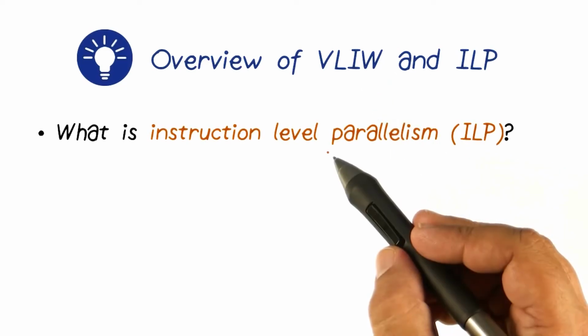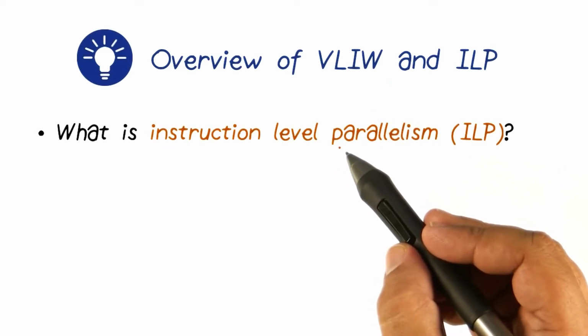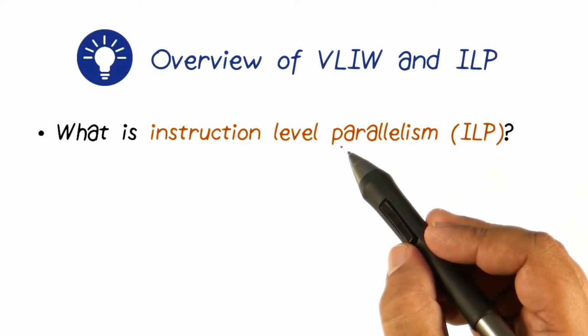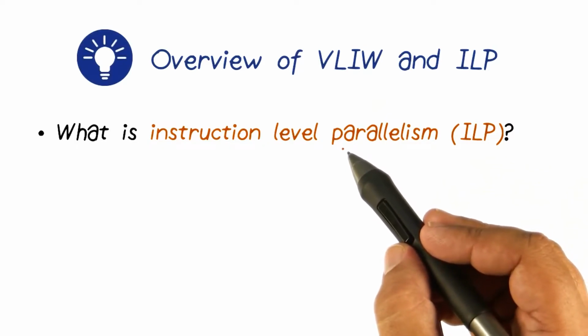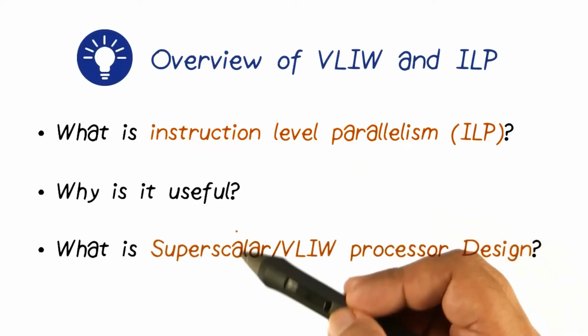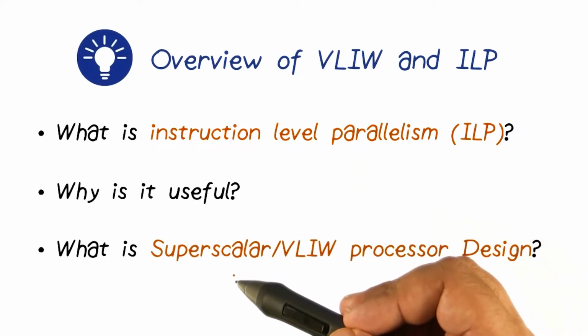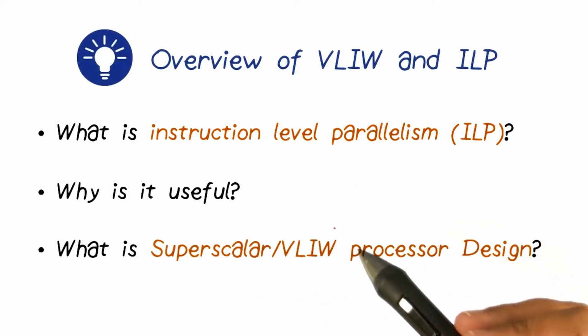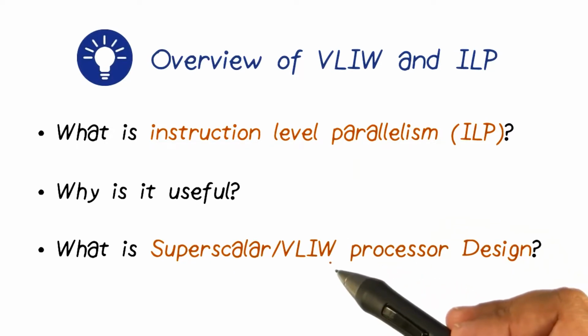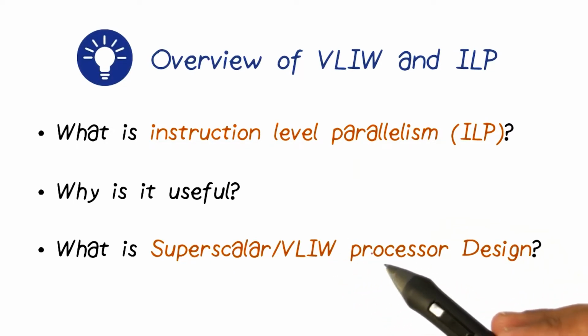The first requirement of high performance is met by instruction-level parallelism, which allows executing multiple instructions simultaneously to increase performance. There are many forms of instruction-level parallelism. The different forms manifest as superscalars, in-order processors, VLIW, and in- and out-of-order execution.